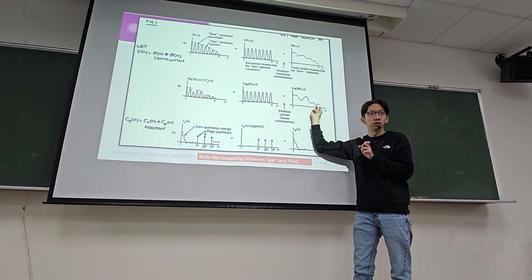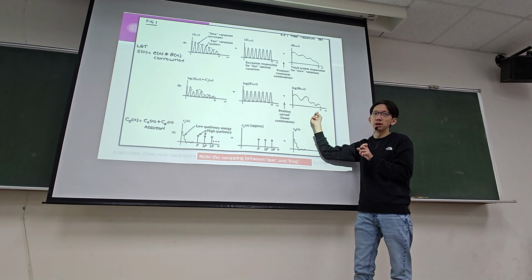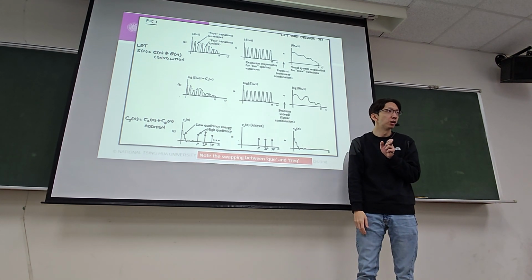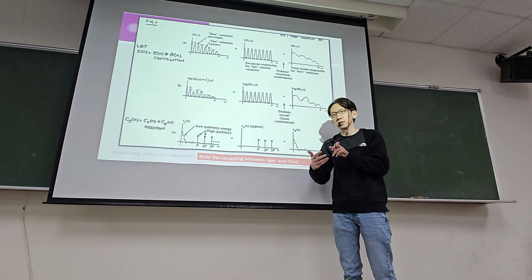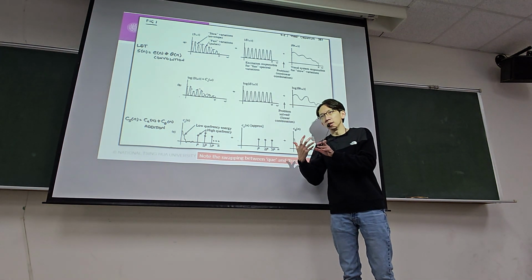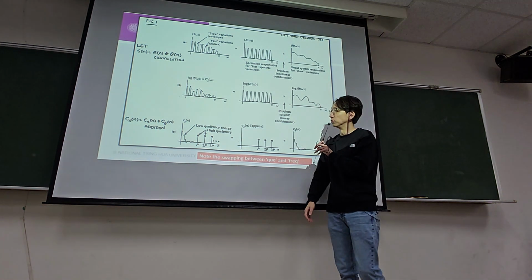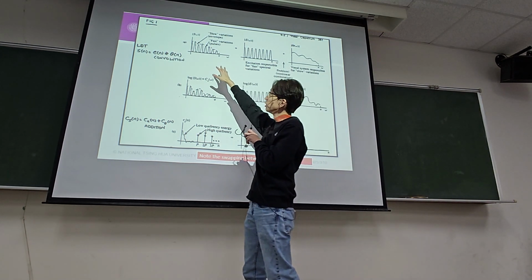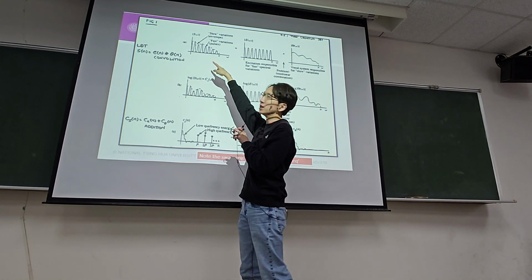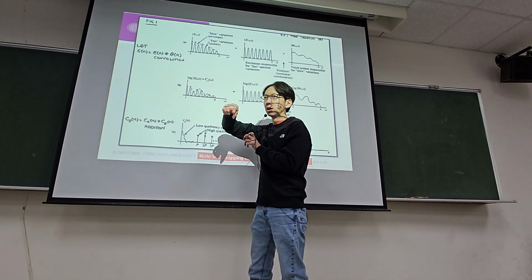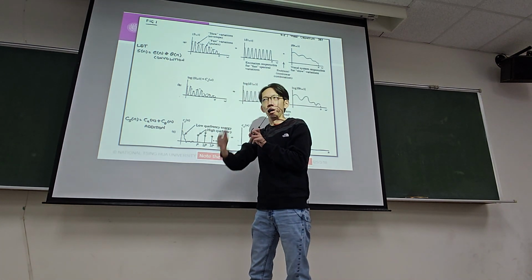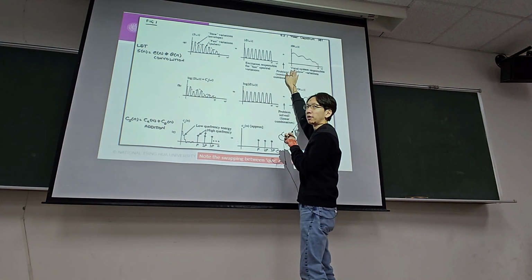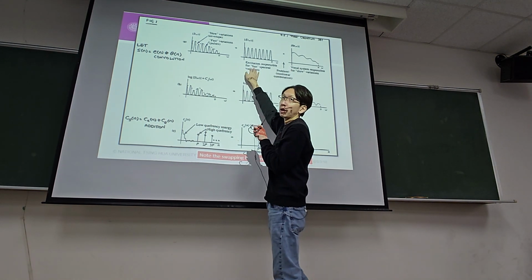So we will derive coefficients that we compute here and take them as input to design our speech recognition system. But this whole cepstrum analysis is built upon the idea of source and filter for speech. So just keep this plot in mind. Any speech signal under a clean setting will always look something like that: some oscillations modulated by what we call the spectral envelope. That envelope is more slowly varying in the spectrum domain, while the harmonics are highly varying.